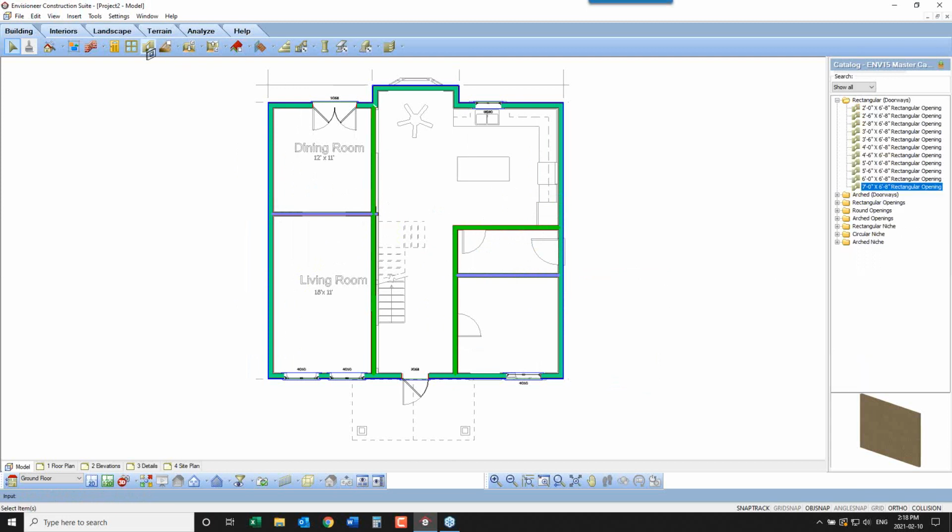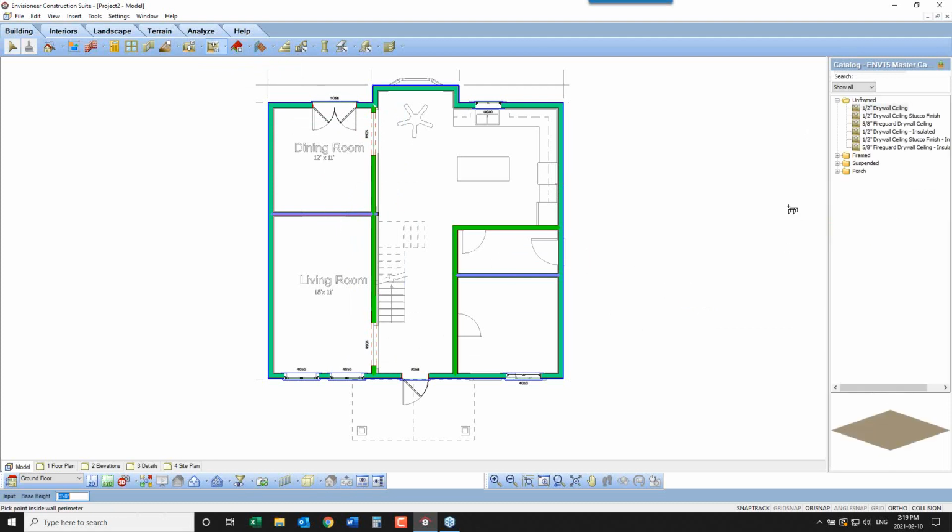So now I have more walls in. I could even put just in a cased opening. So I don't need the window or the door, but I do need an opening in. So I can put in a 5-foot opening as an example, here and maybe here. Does the same thing. I'll get my material count on those as well. And it also gives me the ability to divide those up into rooms. So if you do ceiling material, you could either do it framed or leave it unframed in just the drywall and put the framing and the ceilings in each room.